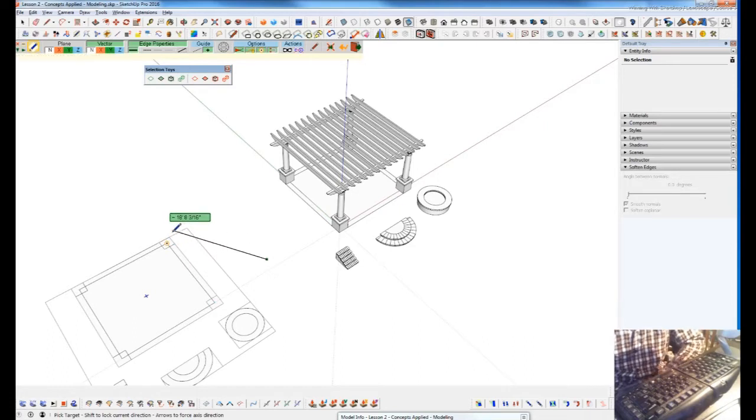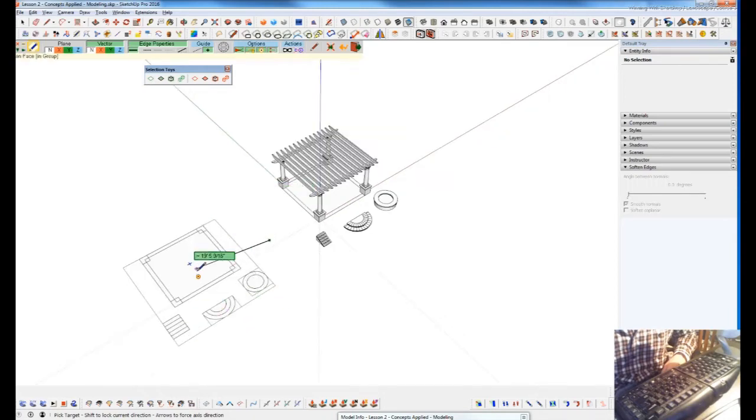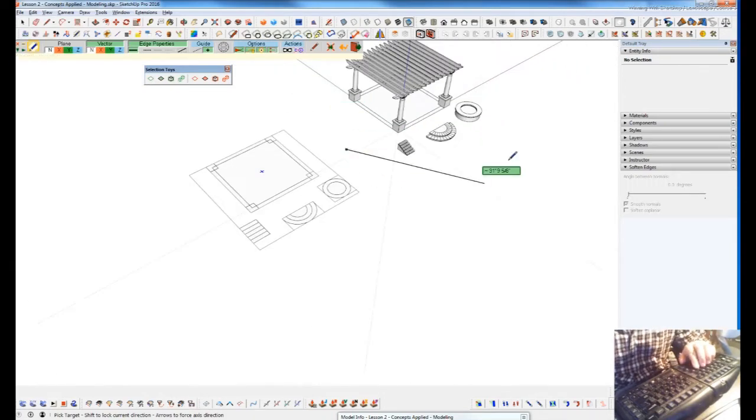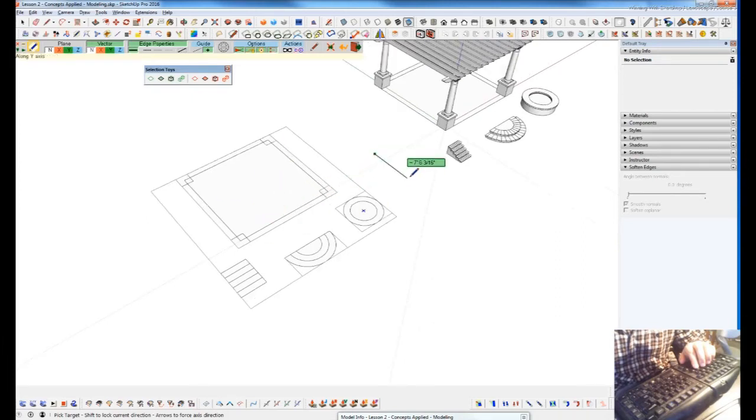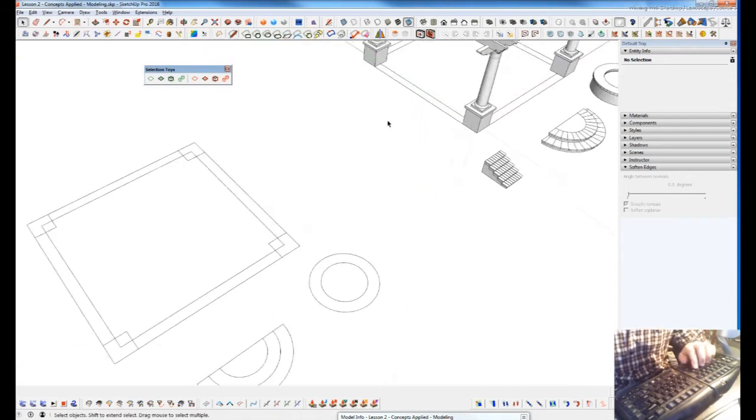And this came out before SketchUp 2016, which will now by default find the center on arcs and things, but it was nice with the draw along that Fredo came out with that it would find that for you as well. So just the edge properties of what you're drawing, how you're restricting that edge as you're drawing it, and what it's finishing as. So it applies this whole Fredo top toolbar and gives you different options.